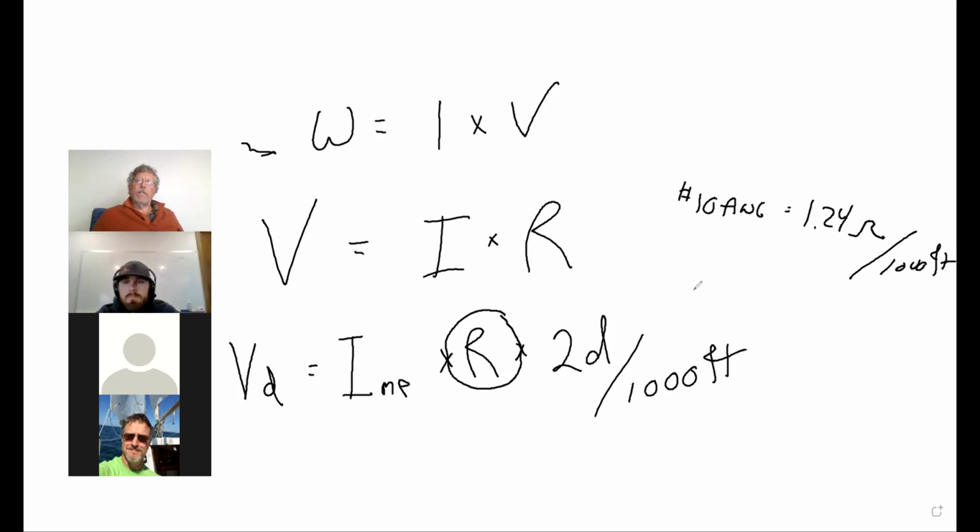So that's going to be the resistance you're going to plug into this equation if you're using number 10 wire. So we're going to use our amps, which we would get off our solar panels. Let's say we've got a string of solar panels and the IMP, or the amps at the maximum power point, is 8.6 amps at that panel. Regardless of how many we've hooked up in a string, remember, when we hook up in a string, the voltage increases, but the amps remain the same. So for each string, it's going to be the amps for one panel, because the amps don't change when you hook it up as a string.